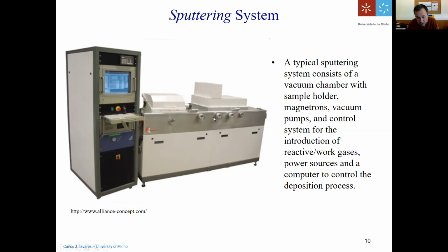a door or a gate valve here that will open or will give you access to the inside of the sputtering chamber, because normally you load your samples through this door. So it's a loading lock here, okay? And when you open this part, inside here it will be atmospheric pressure because air will come in. So you have to close this to always maintain the vacuum inside your main zone where you make your deposition. So you close this gate valve, okay?